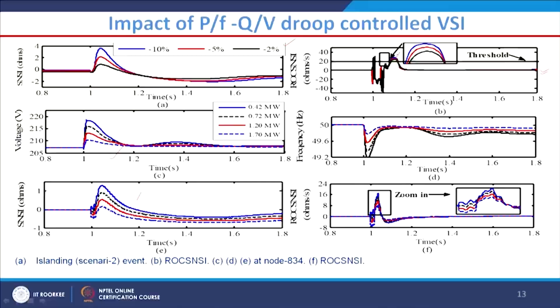It is not a demerit, it is detecting the islanding situation, but it is very close. You could see here it is very close to the threshold, right. And these are for the frequency based relays, and we have also given a comparison with the existing islanding relays. The existing is frequency and rate of change of frequency both together compared, and to some extent this is also oscillatory in nature. It is not as straightforward as what we have seen in the previous results.